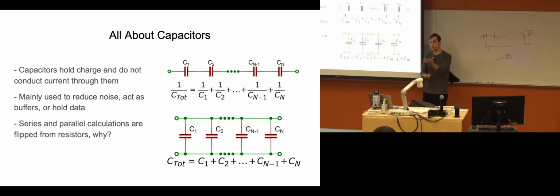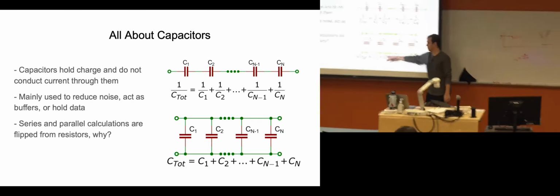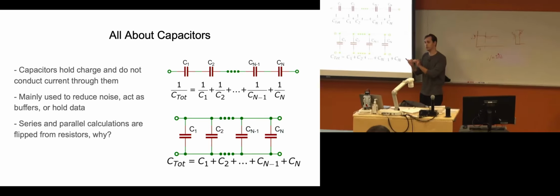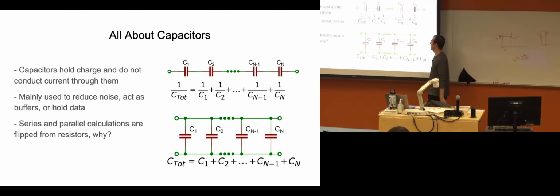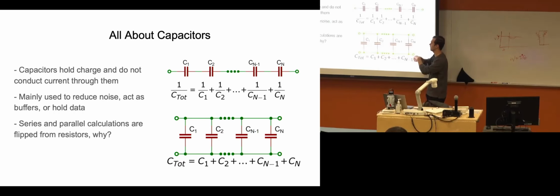One with both. Both, right? So now they're both holding the charge. You have double the charge to supply current, right? So when they're in parallel like this, they're additive, like how resistors were in series, right? And that's just because the total amount of charge they can save just adds up on the same node.